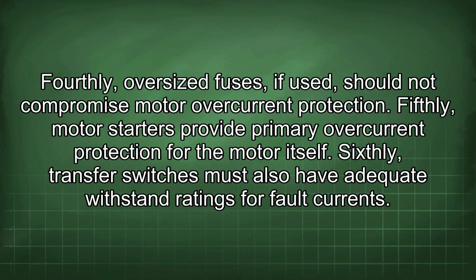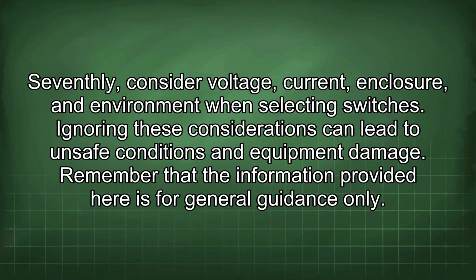Sixthly, transfer switches must also have adequate withstand ratings for fault currents. Seventhly, consider voltage, current, enclosure, and environment when selecting switches. Ignoring these considerations can lead to unsafe conditions and equipment damage. Remember that the information provided here is for general guidance only.